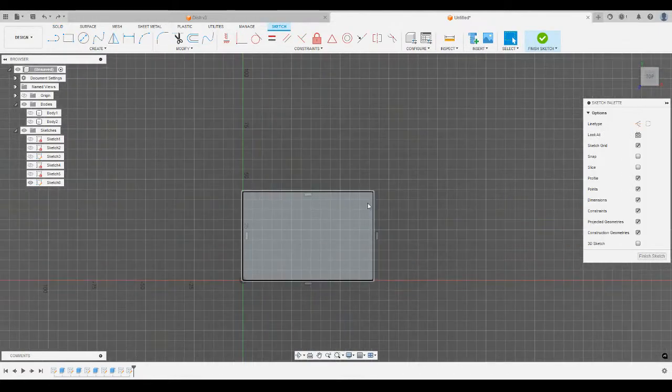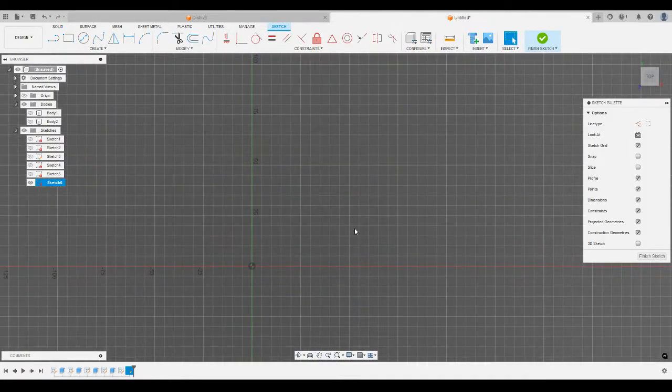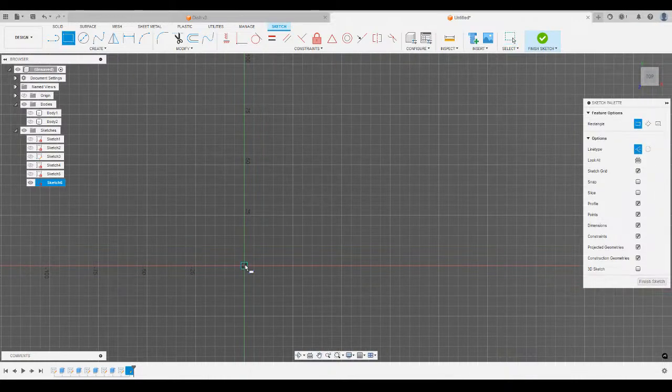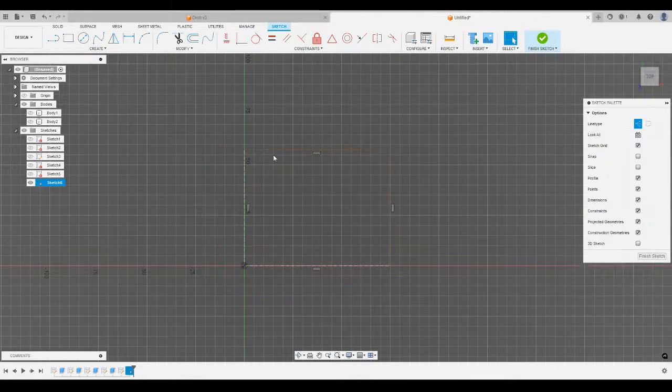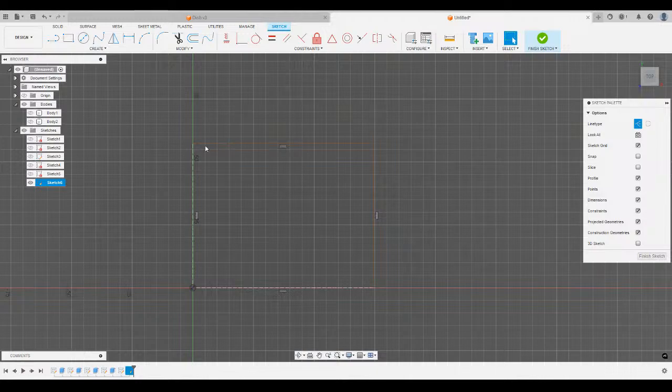But if I hit undo, if I delete this rectangle and I turn on construction geometry, so in Fusion the keyboard shortcut for that is X. You can see it over here turning blue. So you turn the line type to construction, and now I draw a rectangle. See, they changed their color scheme. Now things are harder to see. So it's this orange dashed line. The rectangle is still there, but you can see it's no longer an enclosed profile within it because it's made of construction geometry. So the construction geometry is just there to provide a reference.